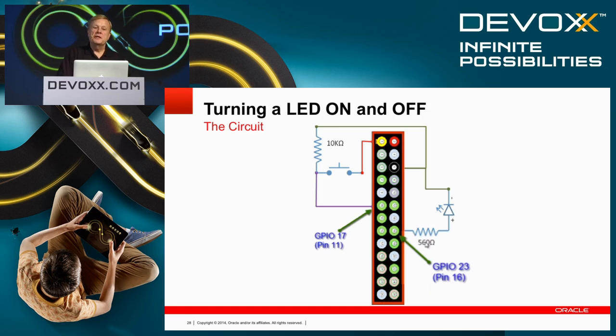So to turn an LED light on and off, we need a switch and we need an LED. If you look at the circuit, in the upper left is the number 1 pin. That's power, that's voltage. Notice it's going through the switch and then through a resistor and back to ground. Pin 6 is the ground.